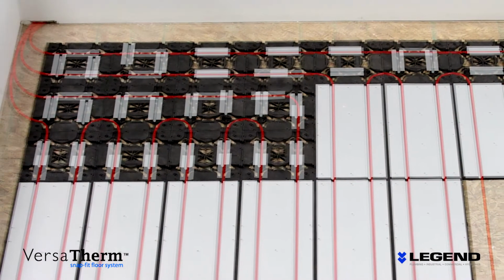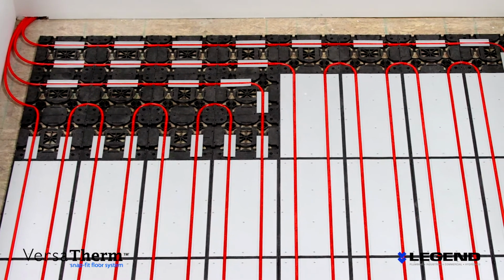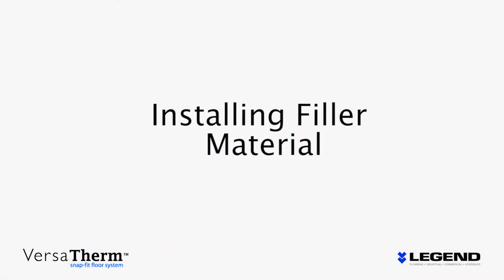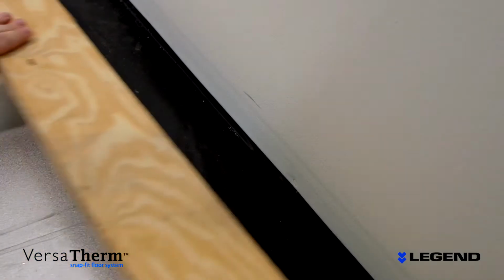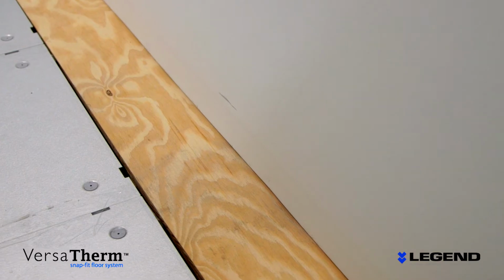Keep the tubing tight to the inside on any bends. This allows for expansion. Perform an air test on the completed system. Install filler material in any spaces around objects and anywhere you will not be heating, such as under cabinets. Use 3/4-inch plywood for the open spaces and your 3-inch perimeter gap.